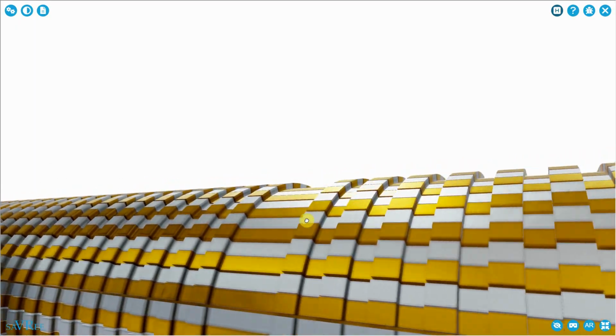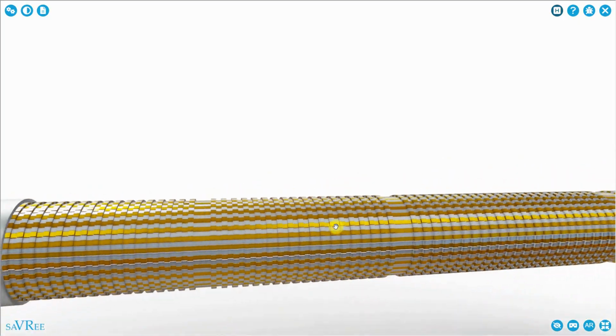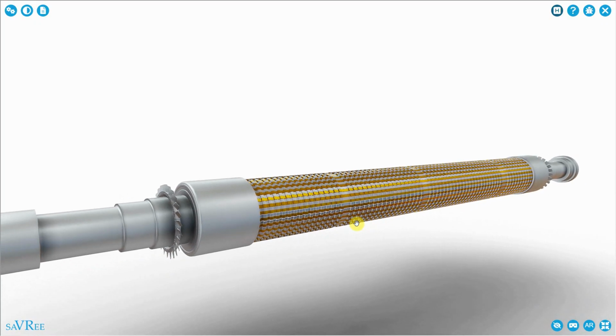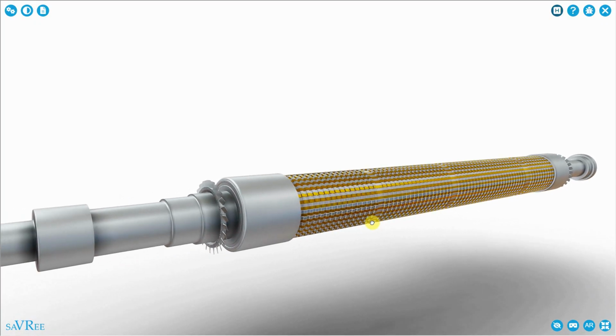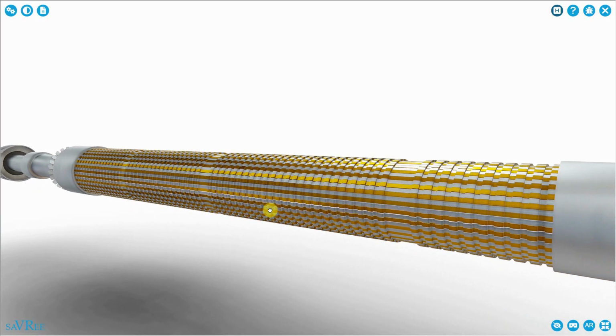One reason why it may have these grooves is to promote air flow or air circulation within the generator. A rotor will often be designed so that when it rotates, it creates some minor turbulence in order to promote cooling. Now, I mentioned air, but air is a cooling medium that's used only for smaller generators. The other type of cooling medium that you'll encounter is hydrogen.